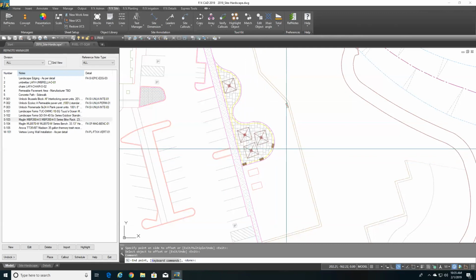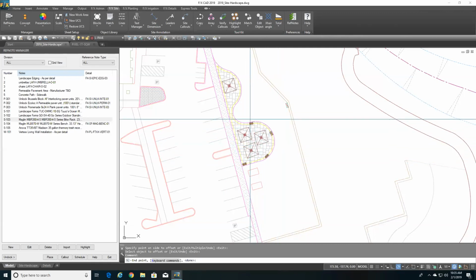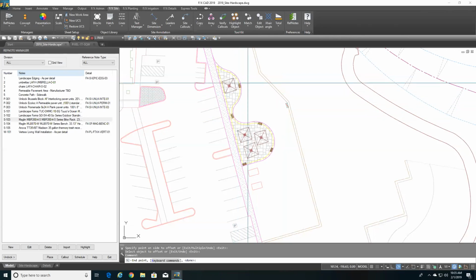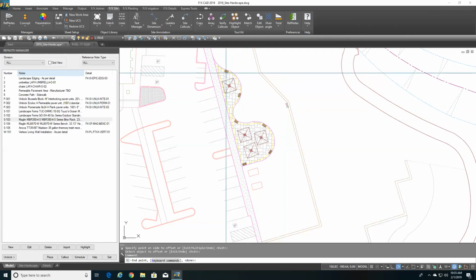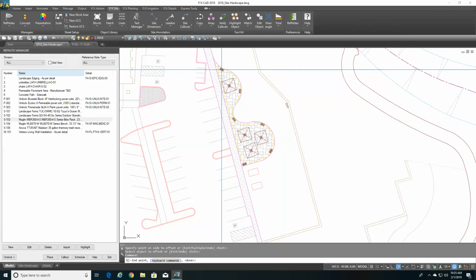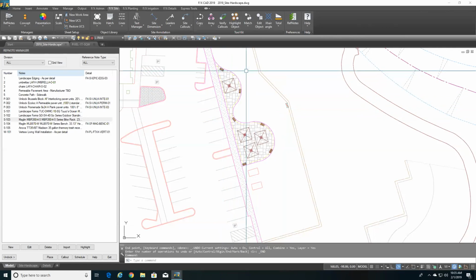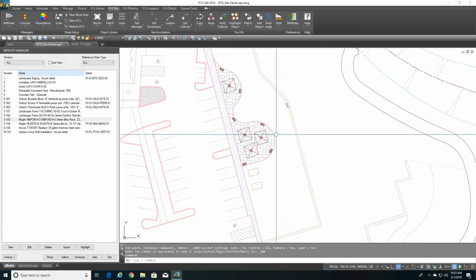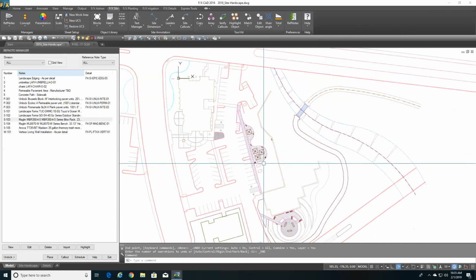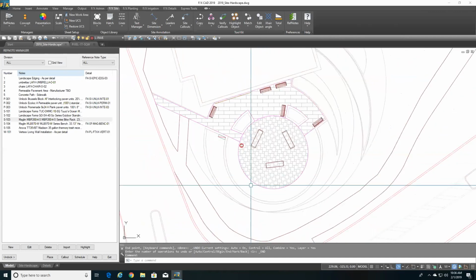And now every 30 feet, a new block is going to pop up along that line, which is super cool, right? So you can be really specific. You can be very to the point about how far apart you're placing things and copying things, and just hit OK. And so now I have 6 bike racks, perfectly spaced, perfectly offset in this hardscape area, which is just such a cool tool, right?